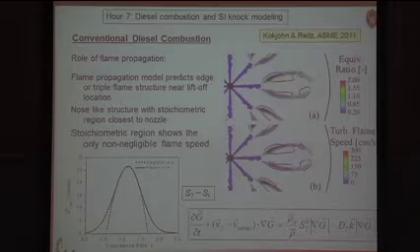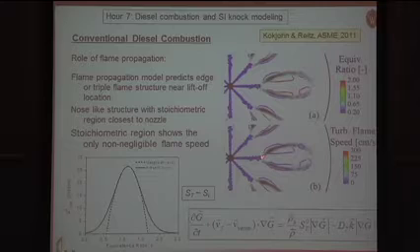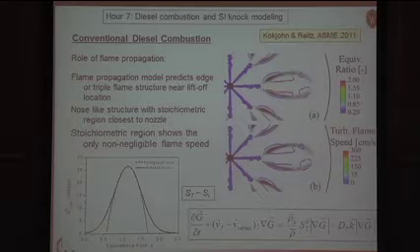If you use a model like a flame speed model, it really only is doing anything in this region right where the flame is lifted. And in fact, you see OH even ahead of that. So you don't really need to consider this flame propagation at all in the case of diesel combustion, conventional diesel combustion. And that explains why we've been able to get very good results without having to consider flame propagation for many years by modeling diesel combustion as just a diffusional mixing with the K epsilon diffusion model of the fuel and the air and a chemical kinetics model where the fuel and the air meet.